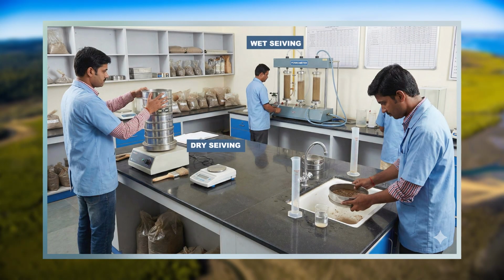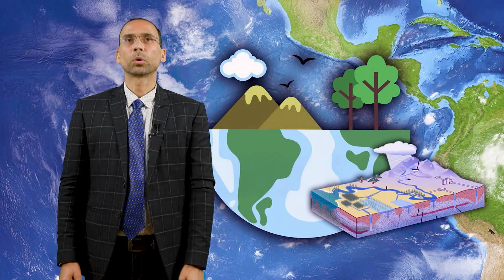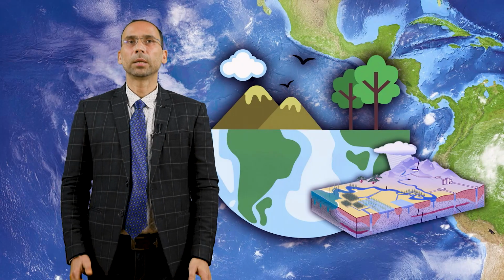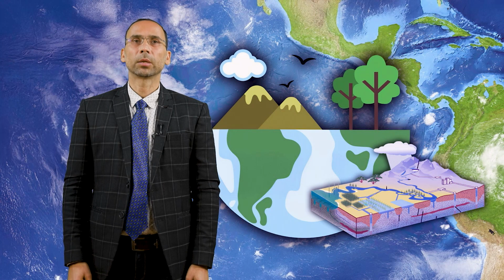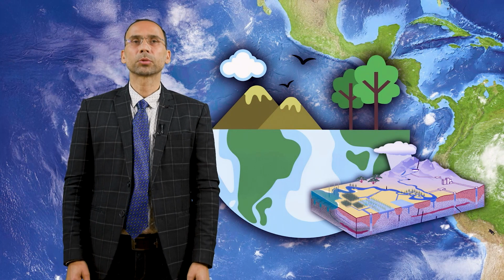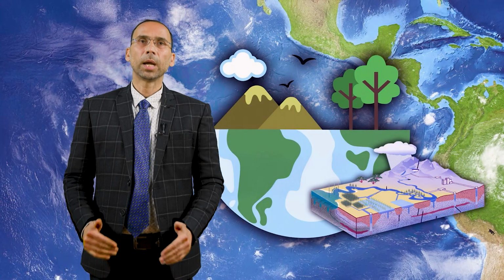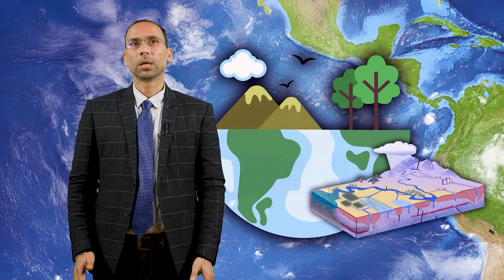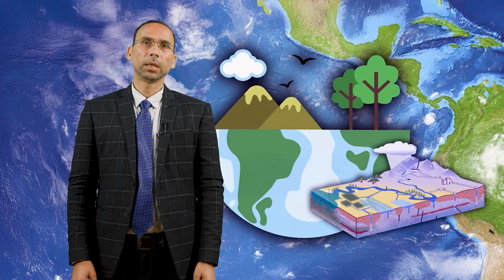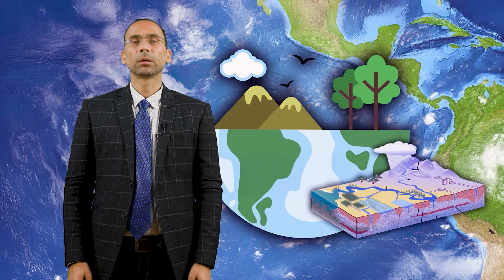Soil and sediments are analyzed for grain size composition using dry and wet sieving methods. Permeability tests are conducted to determine porosity, specific yield, pore water pressure, hydraulic head and saturation conditions in soil and rocks. It helps hydrologists to quantify permeability, conduct experiments on Darcy's law, study liquefaction, etc.